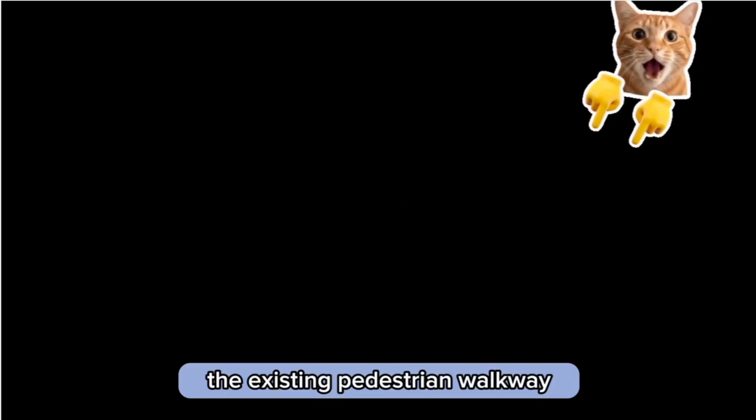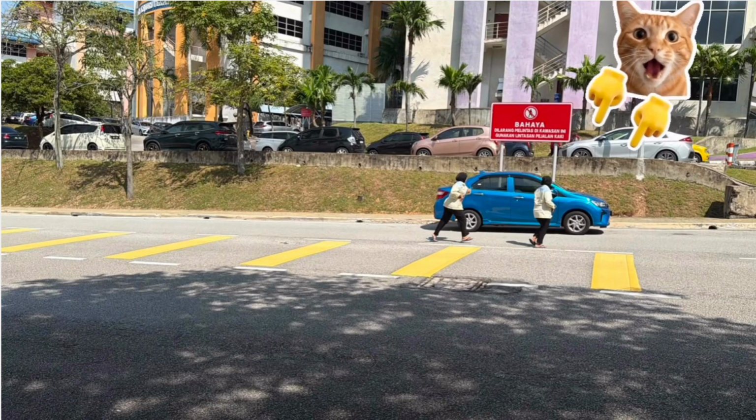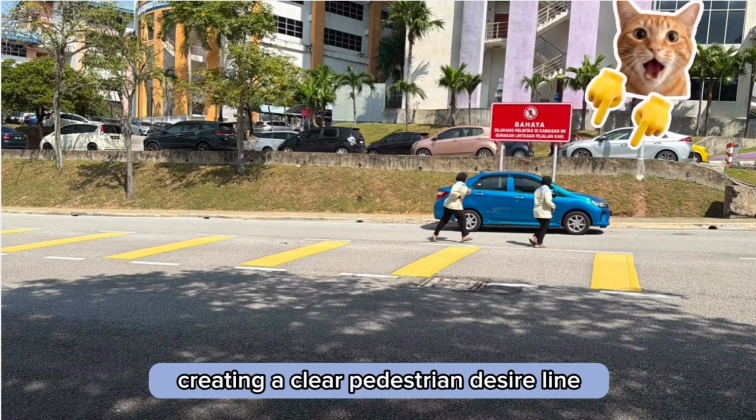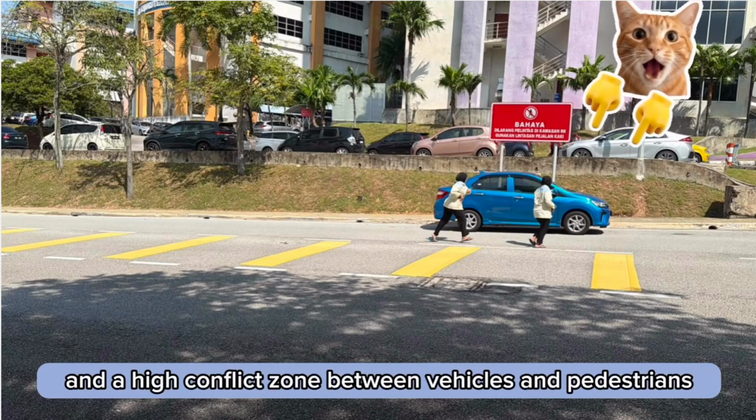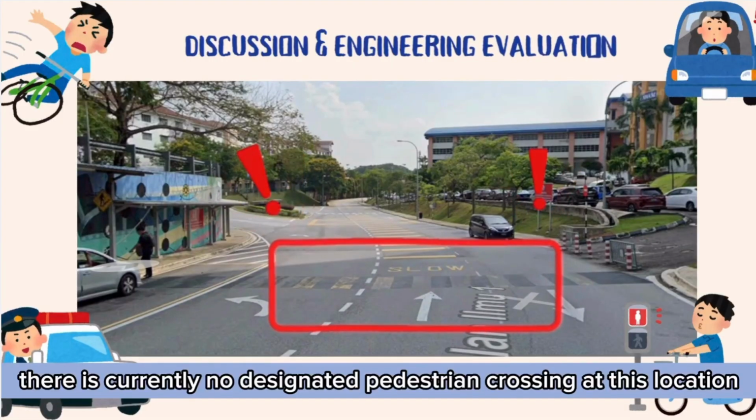hill. The existing pedestrian walkway naturally channels students to cross at the bottom of the downhill section, creating a clear pedestrian desire line and a high conflict zone between vehicles and pedestrians. However, there is currently no designated pedestrian crossing at this location.